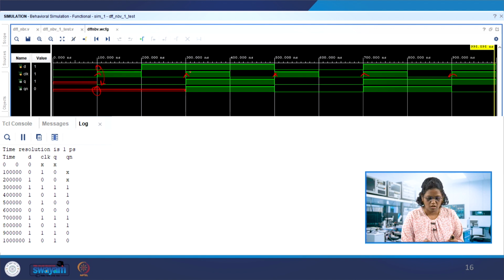At the next passage of the clock, D is passed to Q, that is fine. Again it is passed at the passage of the clock. It works for D alone: D is passed to Q, that's fine. In Qn, what happens? Here Q is supposed to be 1, it is not. Here it is supposed to be 0, because Q is 1, and here it should be 1, and here it should be 0, but the value Qn gets is not deterministic.